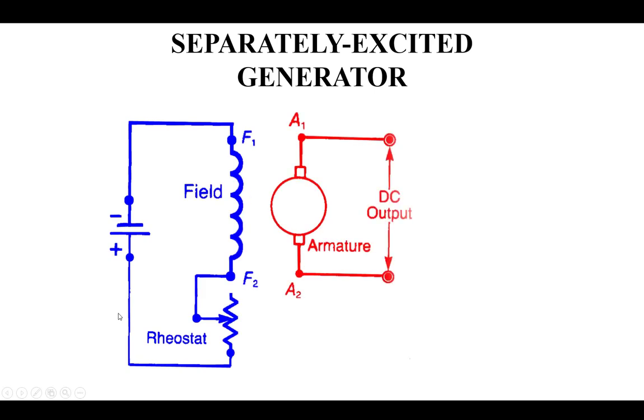A separately excited generator. What's separate is the field. This only means that I'm going to generate voltage. My windings are rotating here, driven by a prime mover, diesel engine, wind turbine, whatever it's moving the coils, and this is my magnetic field. The magnetic field, we know that the output of the generator changes with changes in the magnetic field, flux density, Faraday's law. So if I can control the flux density, the strength of this electromagnet, I can control the output of my generator. And I'm going to control this strength of the magnetic field by controlling the current that's flowing